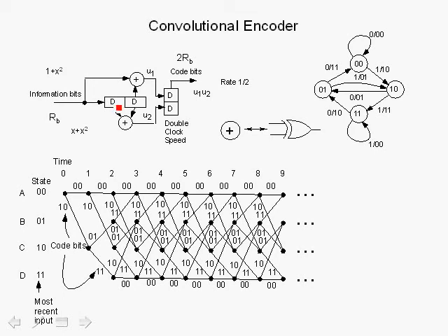So for example, for 802.11a, as we will show, the constraint length K equals 7. So the shift register is 6 bits, and you would have, in fact, 2 to the 6 or 64 possible states for the convolution encoder used in 802.11a.